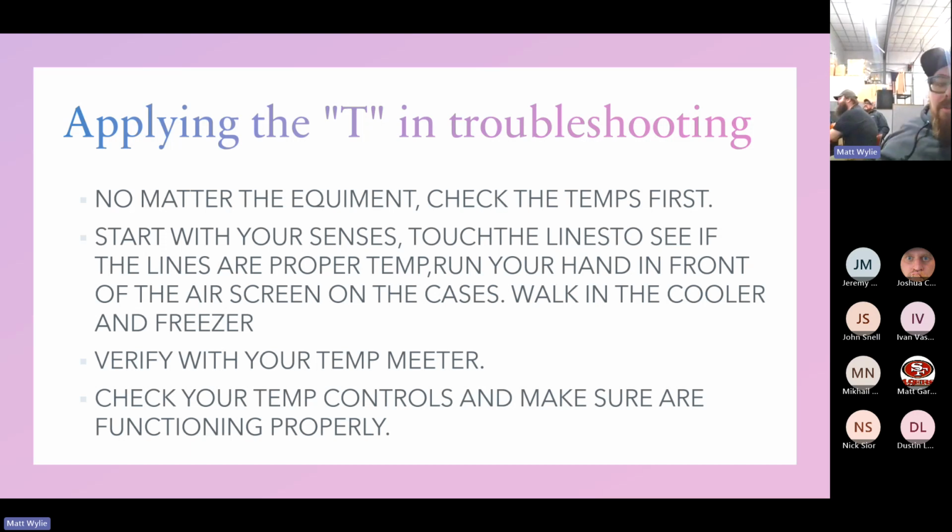Check your temps. Run your hands in front of the air screens, so that's on your open air cases at box stores like Costco, Fred Meyer, Albertsons. Make sure you can feel air coming out of the honeycomb. Honeycombs can sometimes get dirty. Verify your temp with your meter.